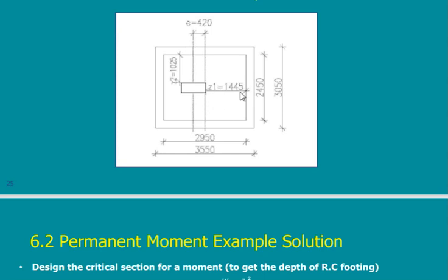So I just calculate the moment here and the moment there, and based on the bigger one I will calculate the depth, and when I calculate the depth I add 7 centimeters the cover to get the T. I make my checks for punching and shear, and once I finish and they are okay, I proceed with the amount of steel and I put the steel.